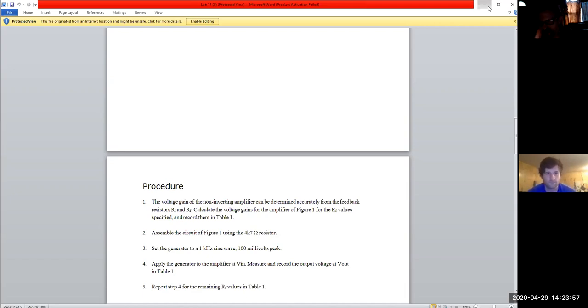And two things. One, go through and change all the electrolytic caps on that thing. And two, change the Zener, and you'll see it on there too. Usually it's a little jelly bean part, right? It's a little Zener in a little plastic case. So you just look on the front somewhere, usually right by where you have to adjust the voltage level for the power supply. Usually right around there, there'll be a little diode model, a 3-legged model on that.